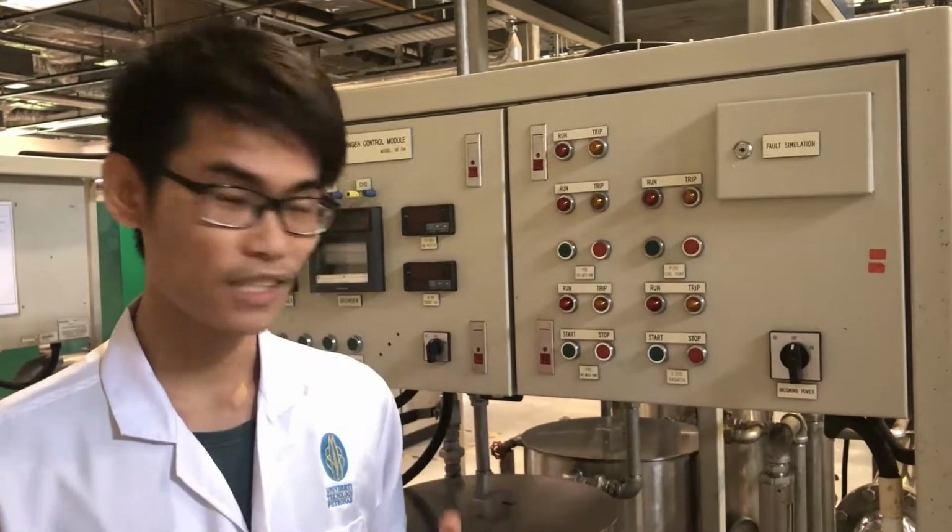I will now explain the theoretical part of the experiment. A heat exchanger is a system used for heat transfer between two or more fluids. Heat exchangers are used in cooling and heating processes. In the heat exchanger, the fluids are separated by a solid wall to prevent direct mixing and contact of the fluids. The hot stream will pass through the tube side, the cold stream will pass through the shell side. The heat exchanger used in this experiment consists of one shell and two tubes. Apart from that, control systems are integrated in this experiment to maintain the desired temperature of the cold stream.